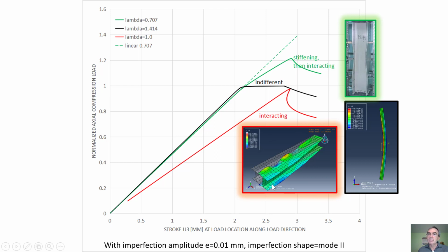All right, so in this picture we see that an Euler mode has developed. I hope you can see the Euler mode clearly, because in this direction X, lateral, you can see from the undeformed to the deformed that it moves a lot. And that is an Euler mode similar to this mode here in black. But unlike this one, it also has a local mode, which I'm sure you can see. The local mode is there. So both modes are taking place. And when both modes take place, all happening at this point, the load capacity of the column will drop a lot with respect to 1. And 1 is probably what you use for the design. So we got to do something about it.